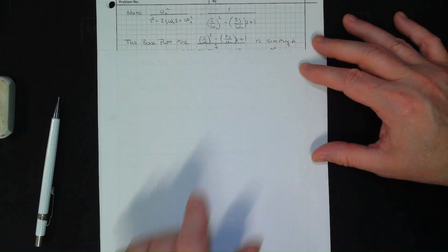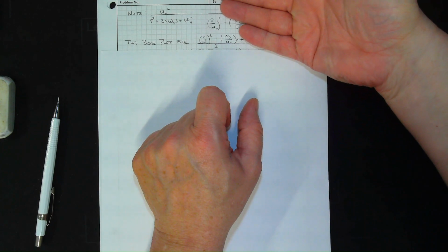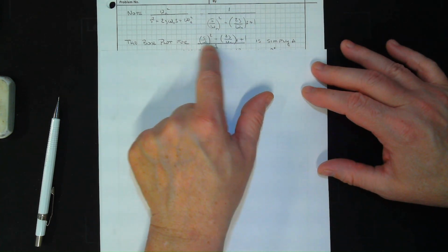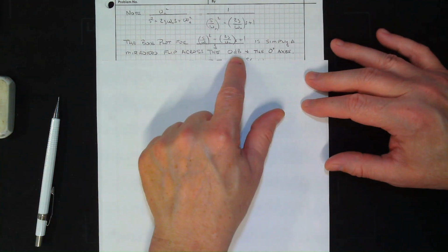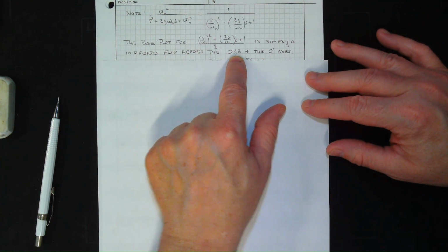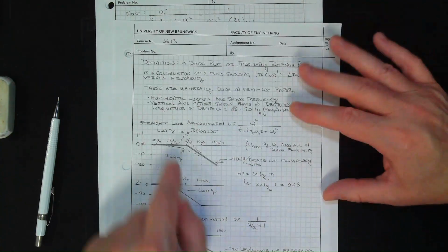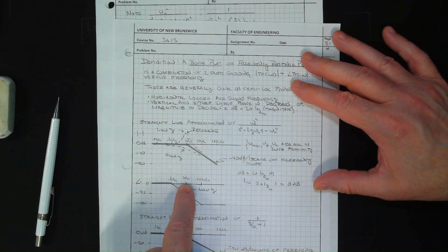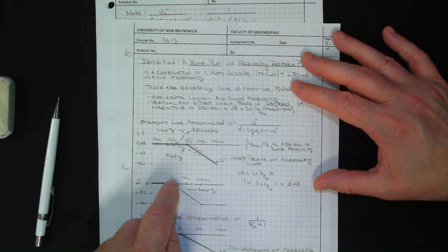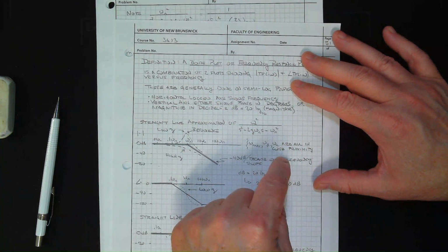Now, what would the Bode plot of this look like? Take this and flip it this way. So now I have 2 zeros over a 1. It's really easy. It simply says mirror across the 0 dB line and the 0 degree axes. So going back to here, if this were flipped, it would go to omega n and go up like so. If you look at the phase, it would start at 1/10 of the natural frequency, go up 180 degrees, and level off.